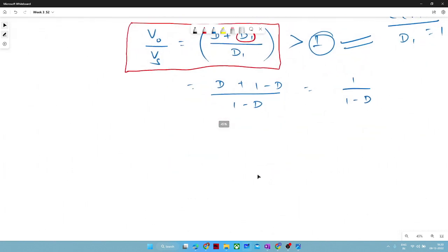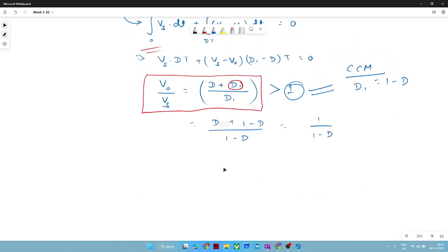We will equate both our diode current in terms of ripple current. So I will write ID is equal to ID average, right? I told you, ID average will be IL into 1 minus D. Or here we are dealing in terms of D1, so IL into D1, right?